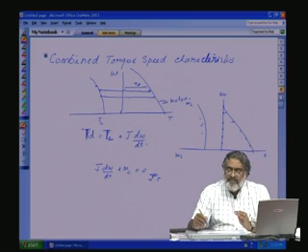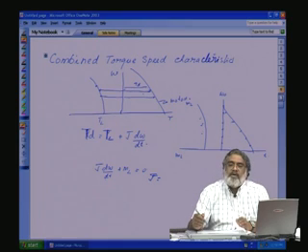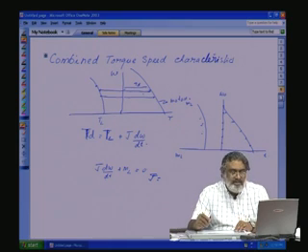In the combined characteristics, we found it is required to modify the motor load torque characteristics through our power converter, such that depending on the load variation, that is TL, we always keep the driving torque equal to the load torque. So, a closed loop control system is required.